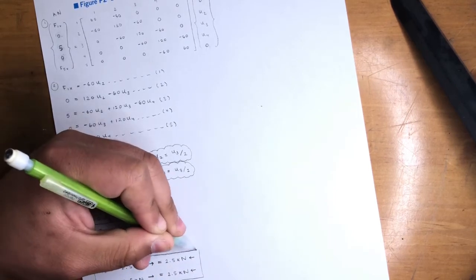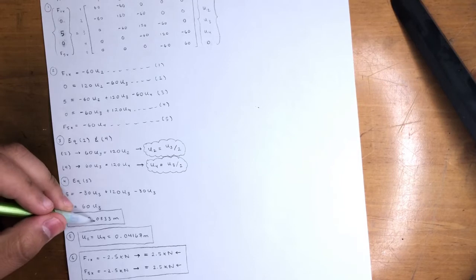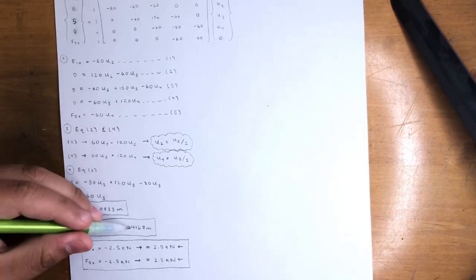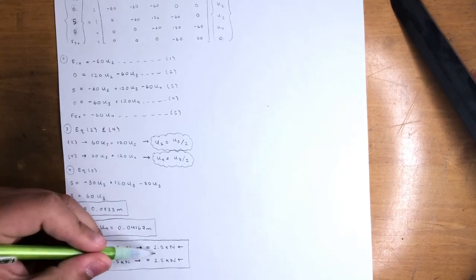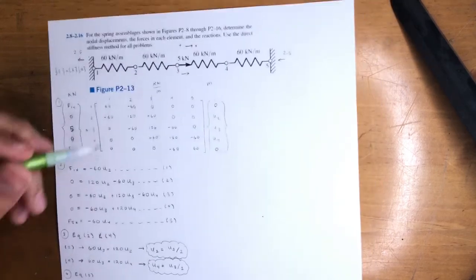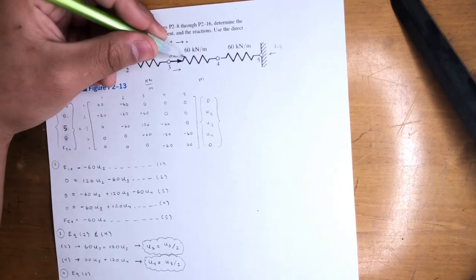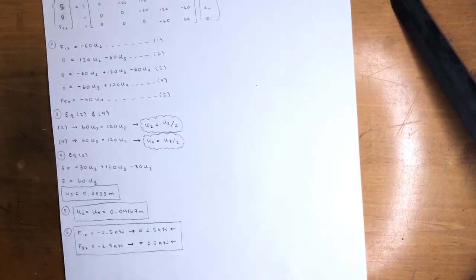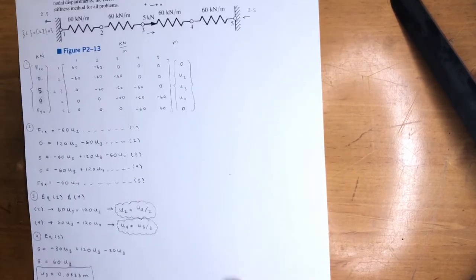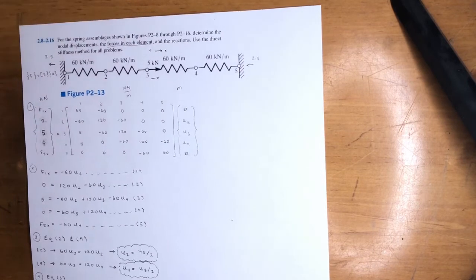We verified the forces. We're not done yet with the problem. What I mean is the force numbers and displacements. So you really can't visualize 0.0833 or 4167, right? Because that's crazy talk. But you could visualize the forces. So that means you did something right if the sum of the forces in the x direction equals 0: 5 to the right, 2.5 to the left, 2.5 to the left. All right, so let's go ahead and do the forces in each element, which is the last step.